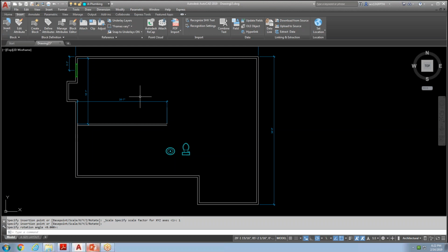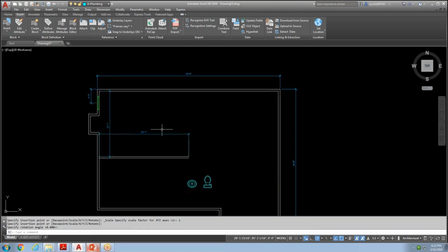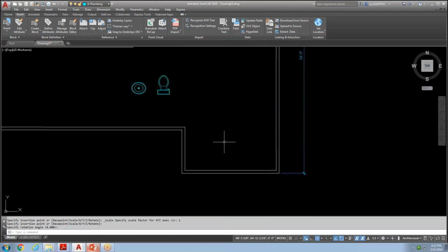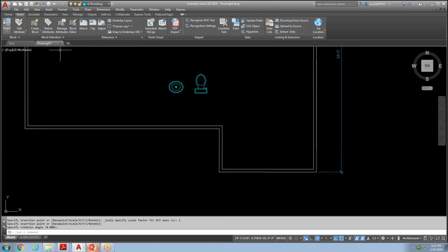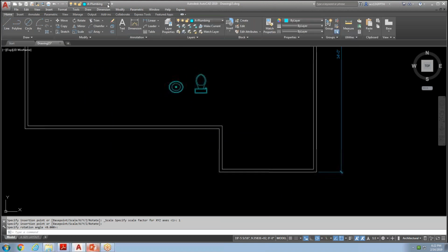And then as far as putting in your doors, you notice your doors are basically 3 feet, okay? So I'll go ahead and just work on this front one right here. And what I'll do is I'm going to go back to here, and I'll go ahead and just put this on the doors layer. I'm going to draw a line here. I'm going to go ahead and start it from here and go over 5 feet. And then I'm going to go here, and that's where the center of the door is going to be. So that's going to be the center of my door.